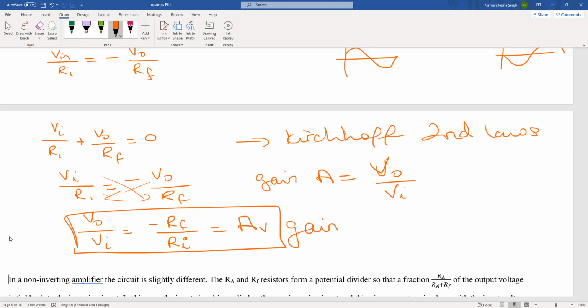All right, so the gain for an inverting amplifier, an amplifier that has a feedback resistor connected to it, is going to be minus RF over RI. Why do we have minus? We have minus because we went through the negative input. So we went from a positive signal to a negative signal. So if you get a negative signal here, you will know that it went through an inverting amplifier. Don't worry about the amplifier being negative and affecting your signal. You're going to have components that compensate for it down the line.